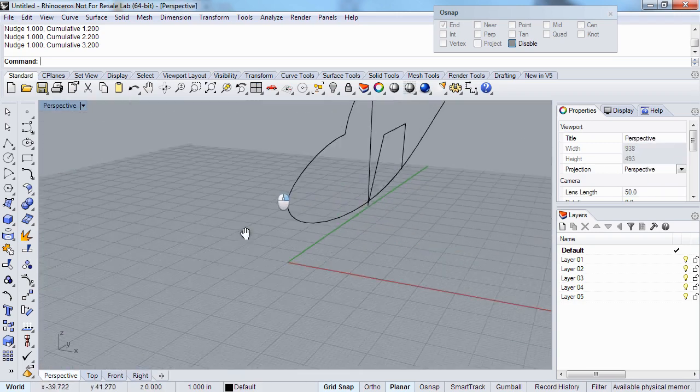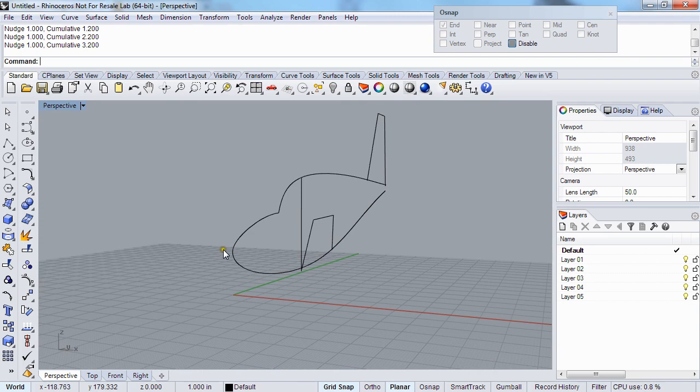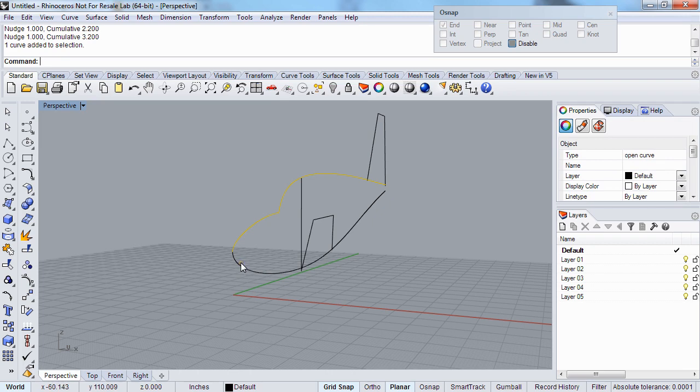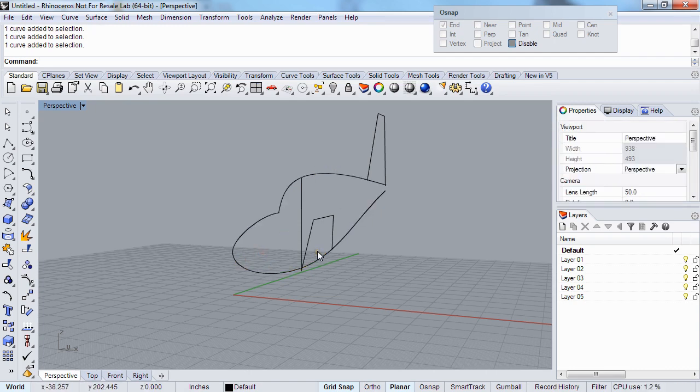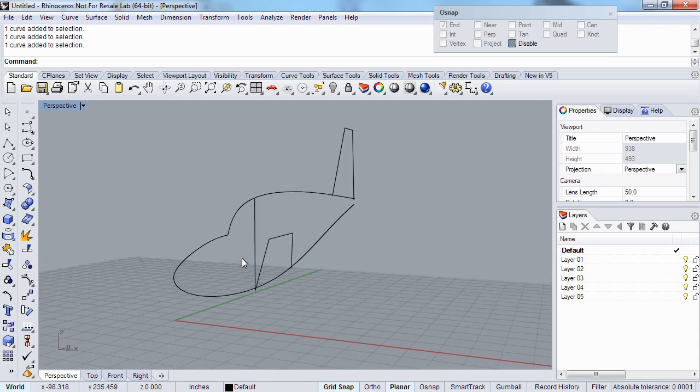What I'm not trying to do, and of course this is the beginner error in trying to make stuff like this, is to say that we're going to make the fuselage of the plane by just taking the top curve and the bottom curve and just sweeping a shape along that. That's not usually going to work. Most vehicles are a lot more complex than that, and if you try, you wind up having to draw a gazillion section curves.